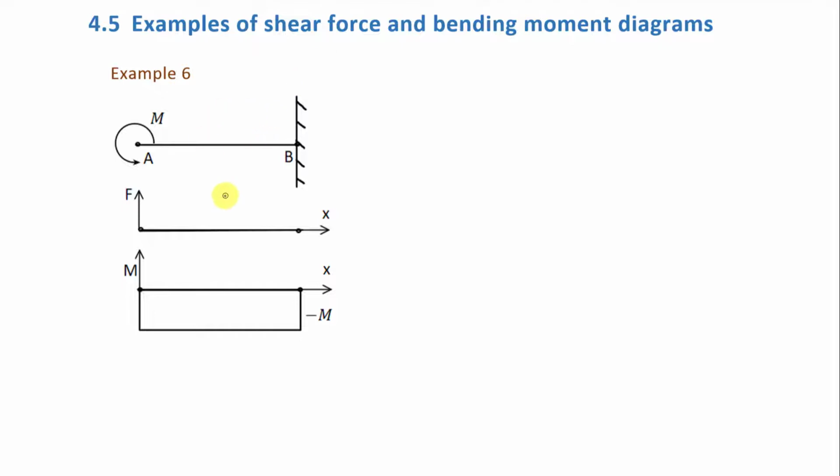So here is the first example. It is very simple. There is one cantilever beam, right? Means the beam is fixed at one end. Normally in the exam, the beam will be fixed at the left end. It will be like this. But to solve the example, we will take it like this. Means we will take the mirror image of this cantilever beam. And why are we taking it like this? Because from this point, we will take this direction as the x direction and this direction as the y direction.